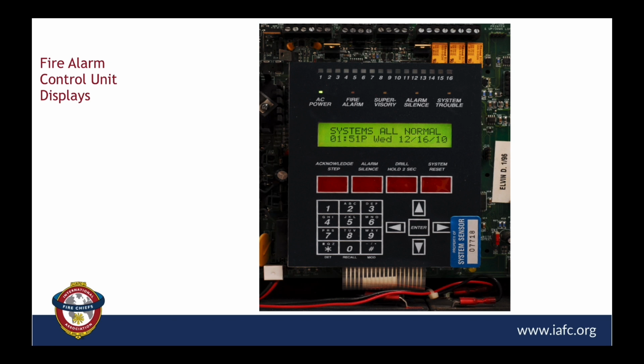One of the challenges I can remember when I was an early firefighter responding to these systems, I'd walk up to it and I would start pushing the reset button. Well, if you hit the reset button first, in most cases, that panel will not reset. You have to go to the acknowledge step, as this one is calling it, and then alarm silence if you so wish to, and then you reset. So it's kind of that 2 steps. We're going to talk about that a little bit more as we go through these different panel configurations.